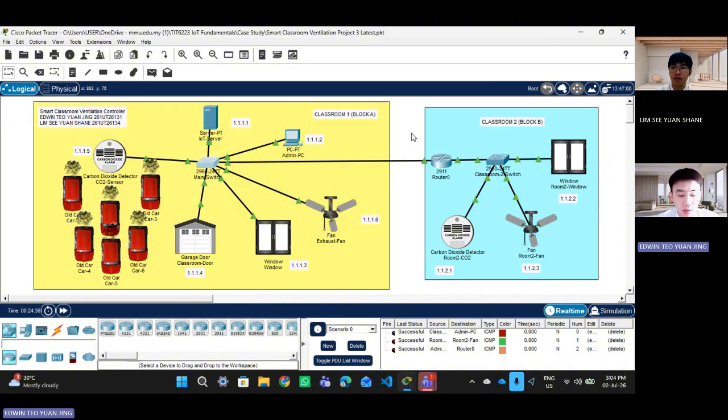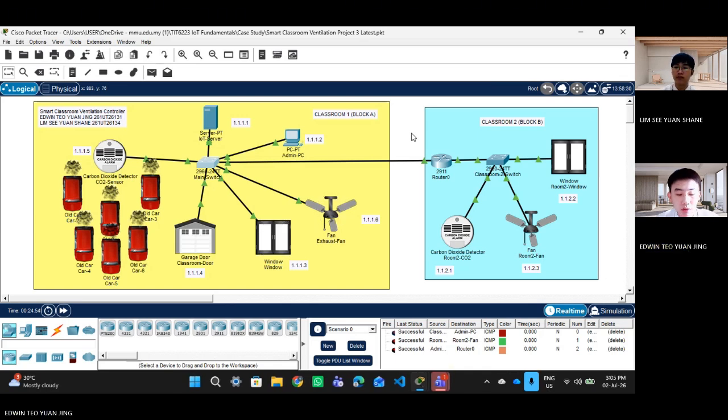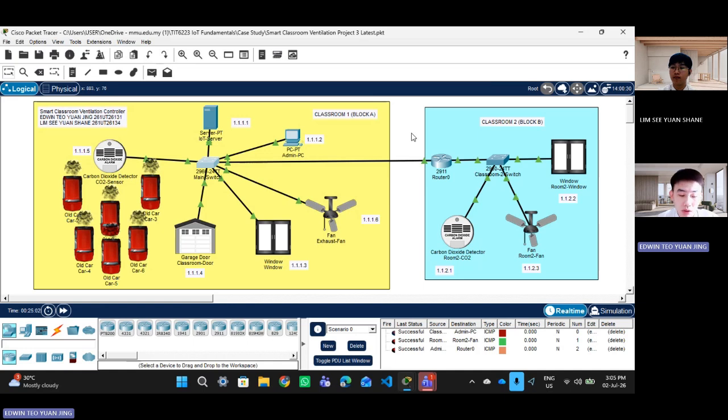It rolls up the garage door, slides open the windows, and triggers the exhaust fans to spin at step 2 for maximum ventilation speed. Once the active extraction flushes out the contaminants and the gas level drops below our safe clearance threshold of 0.5%, the environment automatically winds down to a low power standby mode to protect the university utility budget.